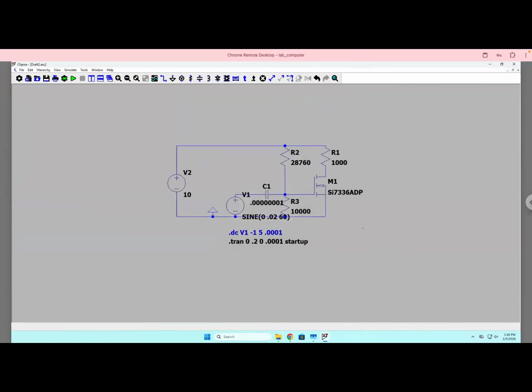Okay, so what's happening is we biased slightly outside of the bias point of the MOSFET, and essentially it's always conducting, which is annoying. Oh, I'm just gonna delete this MOSFET and then try and find one that works.